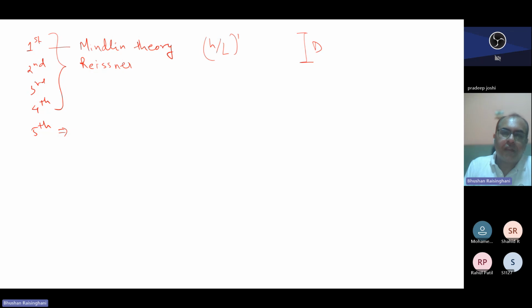Where there is variation along the depth or some complexity, you have to apply a shear deformation theory of a particular order. For that, you need to understand that particular theory. So when I say Mindlin-Reissner theory, you have to go through it and understand what they actually mean by it. Out of plane displacement is independent of the Z coordinate.